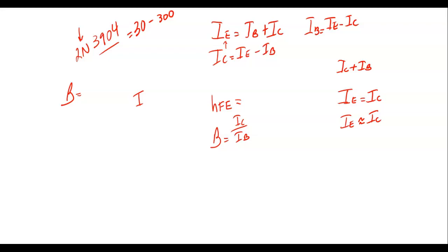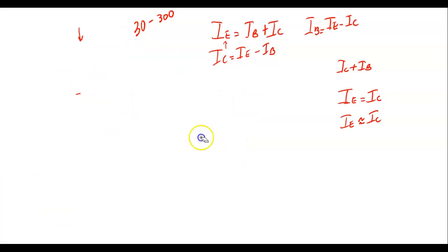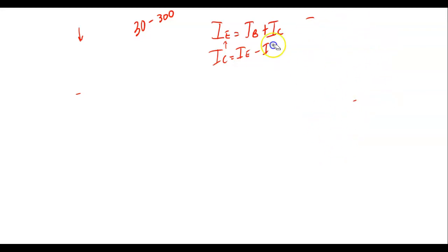Now, the problem we have with beta is that it varies with temperature. So even if I've got a beta, if I don't do anything to take care of this and figure out what I can do to change that, then the temperature varies with beta. So what I did is I came up with a circuit that I've got wired up here so we can look at this. It's a real basic circuit. We've already seen the circuit a couple times. It's a dual voltage bias circuit.